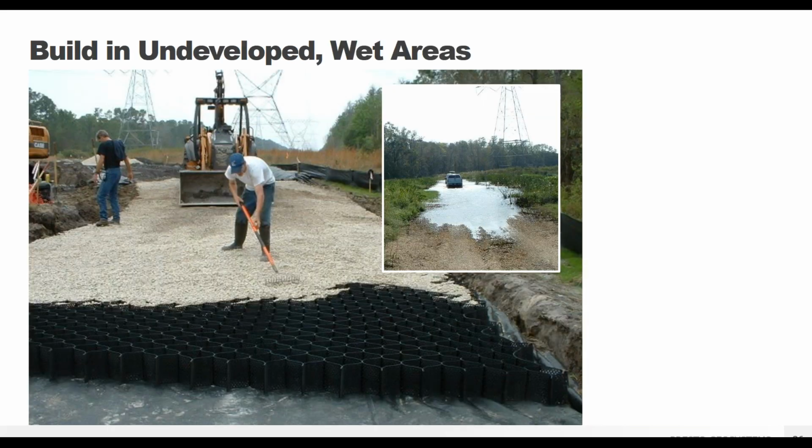And with the GeoWeb panels, you can bridge soft, wet ground, creating access roads with little to no disturbance of the surrounding environment. So saturated soils usually can't support really any type of vehicle load, and adding just a simple geotextile is usually not going to be sufficient, especially since things like geotextiles can get clogged. Especially if you're in a clay environment, they're going to get clogged and they're actually going to prevent that water movement.